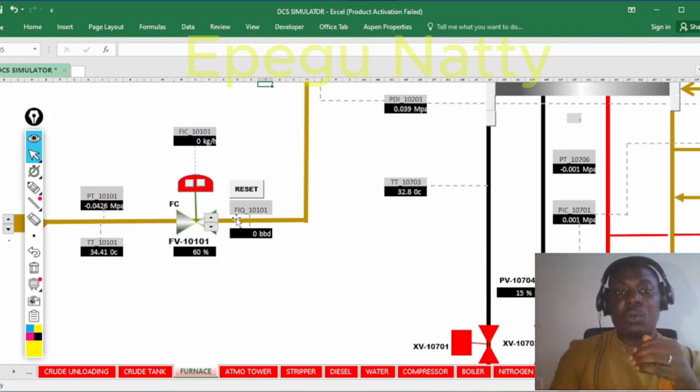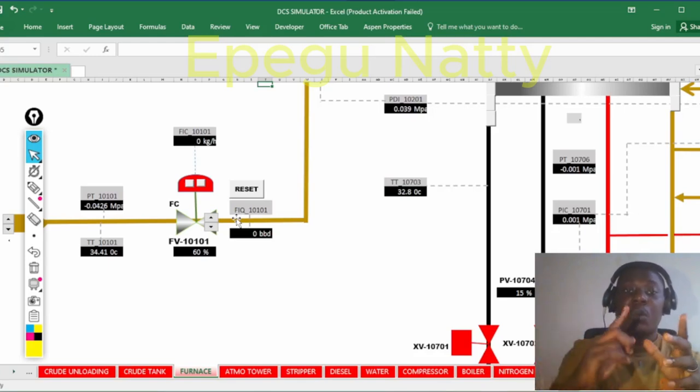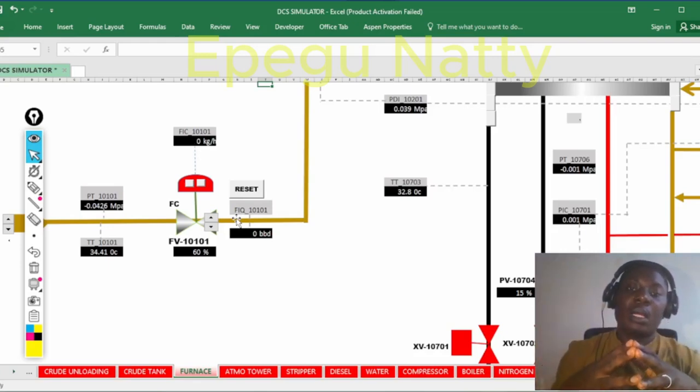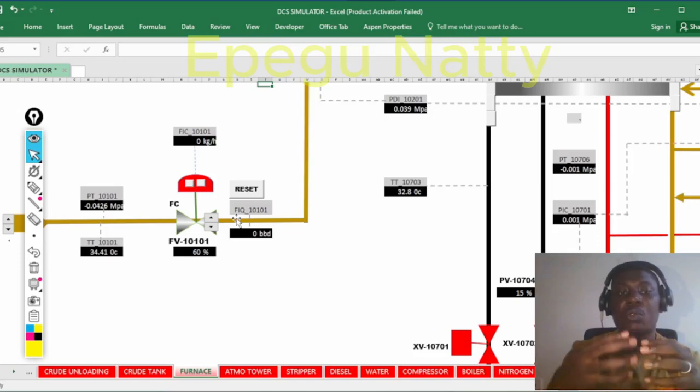I think there was a scenario we had on our plant while we were carrying out an inter-tank transfer operation using a pump. At that point, there was an issue with our air generation unit, so the instrument air got depleted. Once that occurred, the shutdown valve automatically closed.